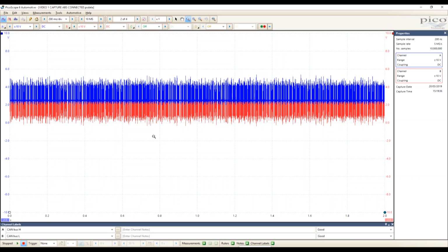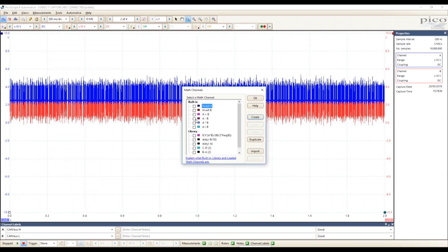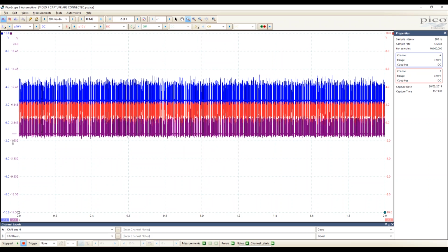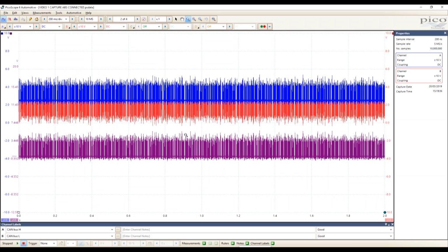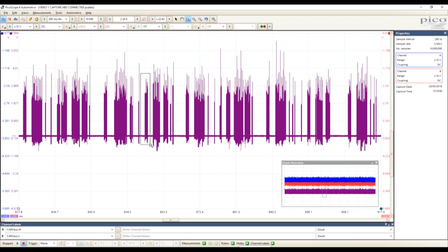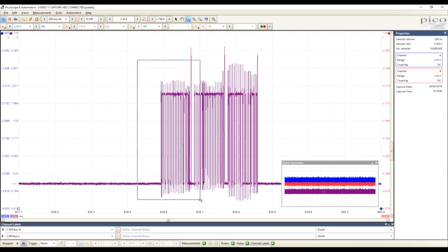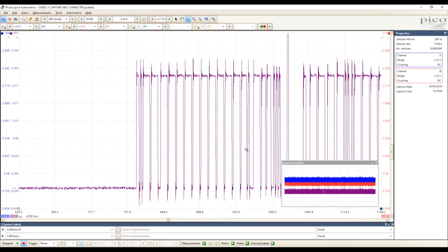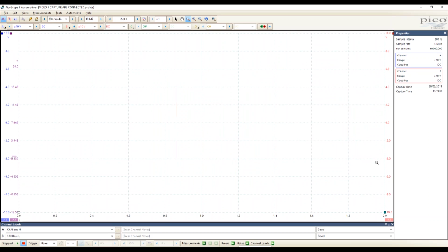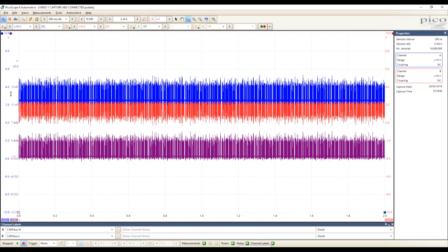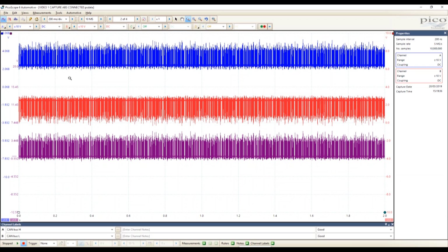Differential voltage conversion. So if we go to Tools, Math Channels, and built into the software, you'll see there, A minus B. Click OK. Now you have a third channel that appears, and it has reduced some of that noise, but if we zoom in on there, this is the exact values that the computer is going to use to decipher what data is being transmitted. And the beauty of that is that it will provide us with the correct channel on which to activate serial decoding.